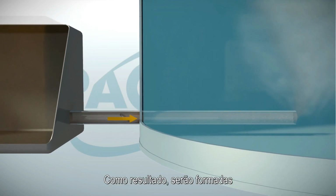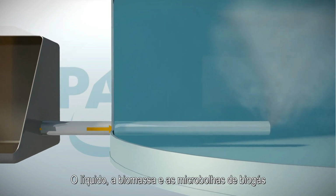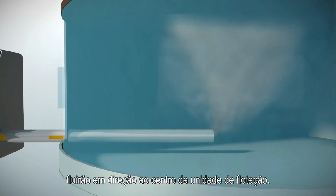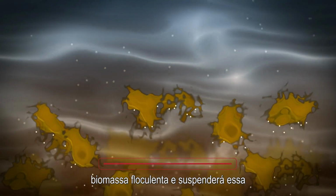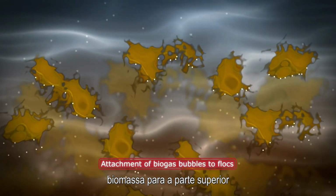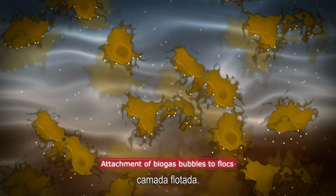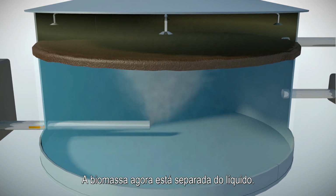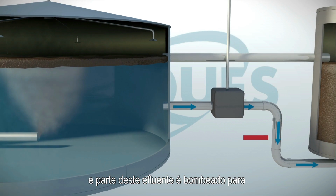As a result, the biogas will form very small biogas bubbles. The liquid, biomass, and small gas bubbles flow towards the center of the flotation unit. The small biogas bubbles will attach to the biomass flocks and will lift the biomass to the upper layer. Here, the flocks are captured in a small flotation layer. The biomass is now separated from the liquid. The purified effluent leaves the AFR system.